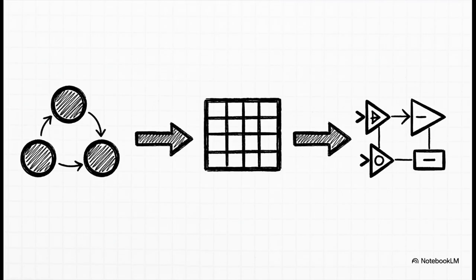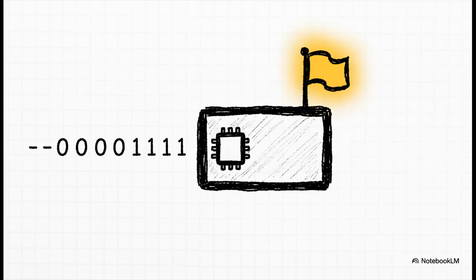Once we have our states defined like that, we just follow the recipe. We draw the state diagram that shows how inputs, the zeros and ones, move us between S0, S1, S2, and S3. Then we convert that drawing into a state table, then an excitation table, and from those tables we can derive the exact logic equations we need to build our final circuit. And what do we get at the end of all that? The payoff. We started with a simple idea, find 3 ones in a row. And by defining states and following this methodical design process, we end up with a tangible, physical piece of hardware that does exactly that. It's a machine with a memory and a purpose, all born from pure logic.